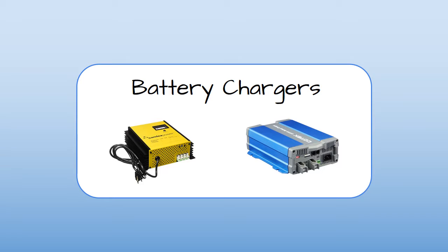The 80 amp units could make you think that the 15 amp breaker in your panel can't handle the current. Remember, the 80 amps from the charger is at 12 volts, or roughly 960 watts, because P equals V times I. The 15 amp breaker is at 110 volts AC, which means that the breaker can handle 1650 watts of load.